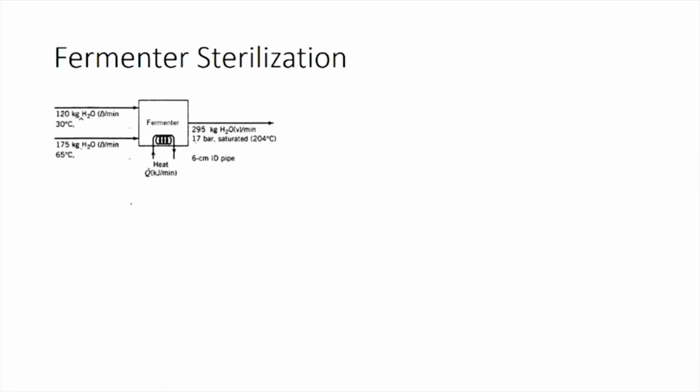This being an open system, the general energy balance equation would be delta H dot plus delta E k dot plus delta E p dot equals Q dot minus W s dot. We cannot ignore the kinetic energy term because we have been told that only the inlet kinetic energies can be ignored. So, we have to calculate the outlet kinetic energies. So, this term would exist. Obviously, delta H dot will exist because you have change in enthalpy due to phase change and also due to temperature change.